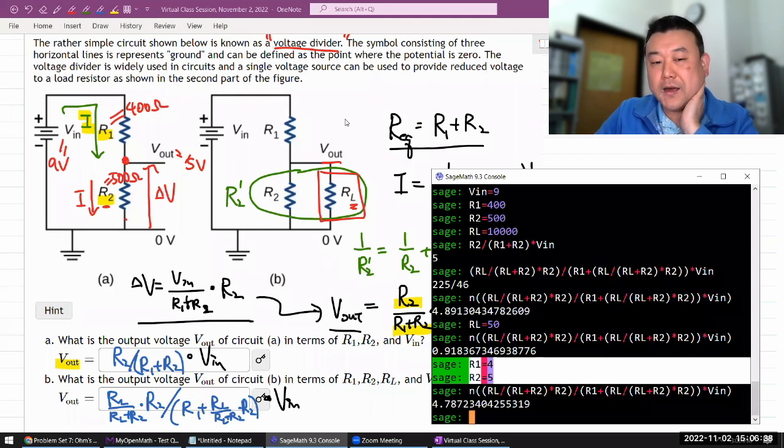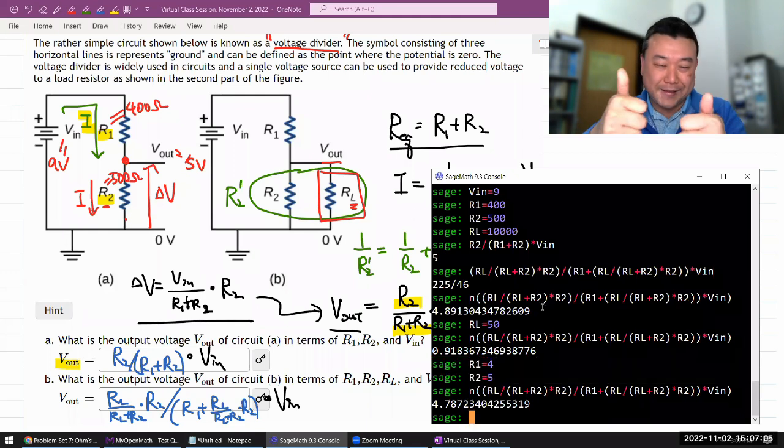Just using a voltage divider is a great way to get a particular value of voltage that you are aiming to get, and there's application of that all over the place. It's not a very practical or efficient way to make a voltage regulator that will reduce a particular input voltage to a lower voltage as a kind of power source. So anyways, I wanted to cover that. So I've done it now. I don't need to do it again.